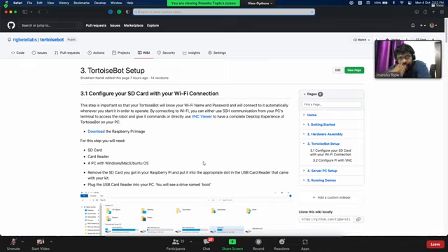Okay, so for that you need the odometry value of your robot. In IRCKT, what you did was you just told it to go forward for a couple of seconds. That is what you did, right? So apart from that, you used to give the odometry value. So you have to provide the position of the robot, and based upon that position, you used to tell it, the robot is at 0,0, go to 1,1. So after that, it used to calculate and go. So similarly, that 0,0 and that 1,1 are the odometry values. So you get odometry from your robot.